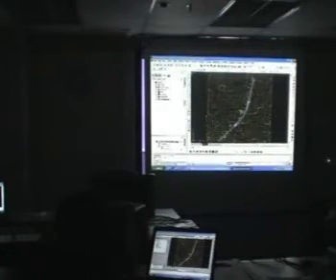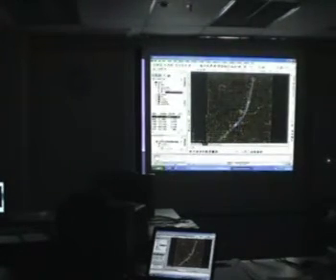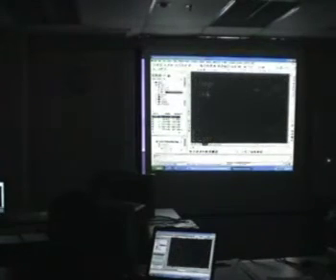On the Prospector, the Prospector basically contains the data that exists inside this drawing, like points. Okay, we've got all the points. If I click Points, you can see all the point information here. The advantage to this is that it's a lot easier to modify. Like in Land Desktop just now, remember I wanted to edit a point description. Let's say in this case we've got point 1248.